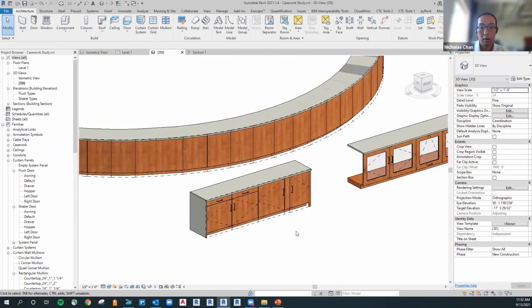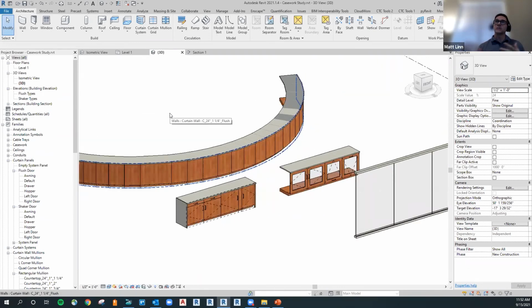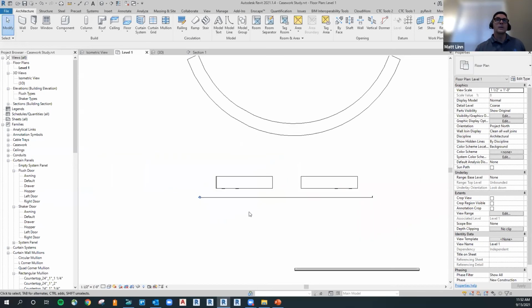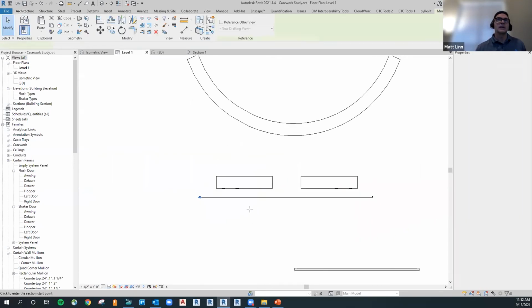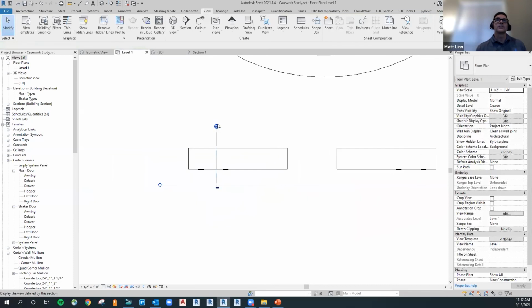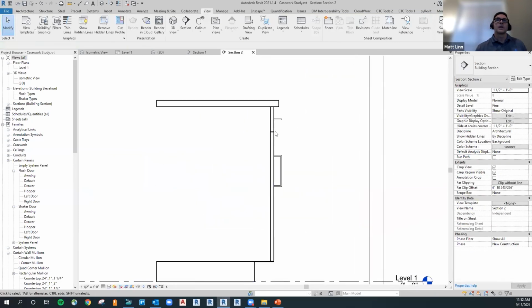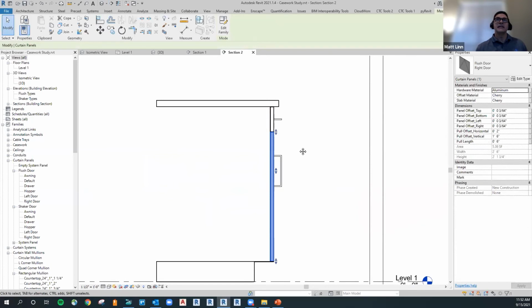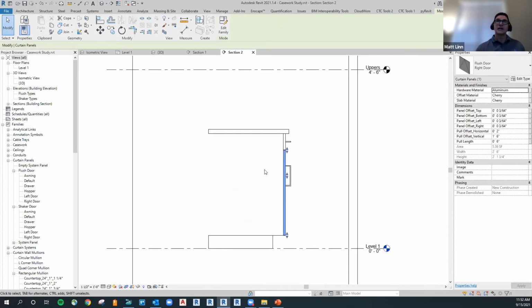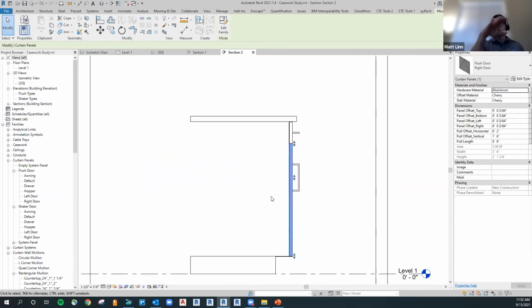So Nick kind of alluded to this earlier as well. In this instance, we're not physically modeling it. We did have an instance in the beta version, working with Eigelberger, where we went in this section here and modeled this piece in the family to have symbolic lines. The symbolic lines would show shelves, and we had some yes/no parameters for 1, 2, or 3 shelves, and we'd space them equally and all these different things.